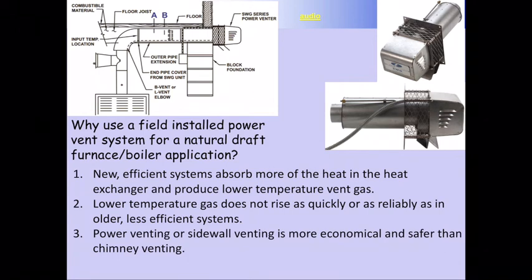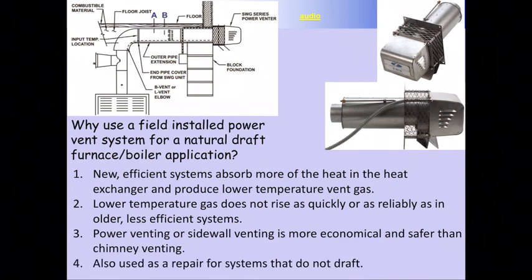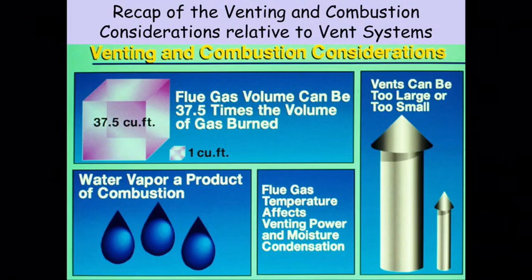You could have a system where that was their design. They decided, we're going to do this as a sidewall application, and no problem. So it allows you to take something that is not designed necessarily to be a power vented application, but make it power vented, and it's less expensive. And again, it can be a repair item that we could use on there that just can't get it to work right.